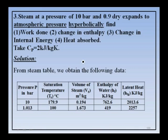Hyperbolic process means PV is equal to constant. That means the product of pressure and volume before and after the process remains the same. That is called the hyperbolic process. So, the first problem on the hyperbolic process: steam at a pressure of 10 bar and 0.9 dry. First you should identify the initial condition of steam. 10 bar and 0.9 dry means it is wet steam, expands to atmospheric pressure. See, this is important. There is an underline here, atmospheric pressure, that is, the final pressure is atmospheric pressure.